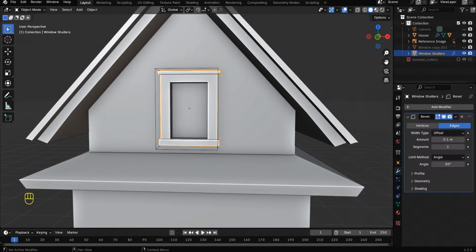Okay, let's add a bevel modifier on this son of a gun down here. Bump the segments up to 2 and bring that amount down to whatever you want. If you want something to look stylized, you're really going to want to run with the bevel modifier. It just kind of rounds out all of the edges.